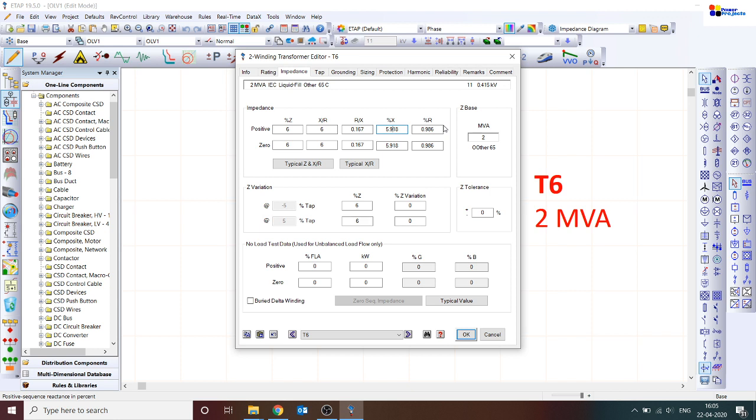Let's take a circular conductor and apply a DC voltage. The current flowing through the conductor, which is a DC current, is uniform, which means the current density is uniform across the conductor. Whereas if we apply an alternating voltage, the current distribution in the conductor is not uniform. Thanks to skin effect, the current concentrates more on the outer surface. The tendency of the alternating current to concentrate on the outer surface is the skin effect. So when an AC current flows in a conductor, the current flow is not uniform across the conductor.